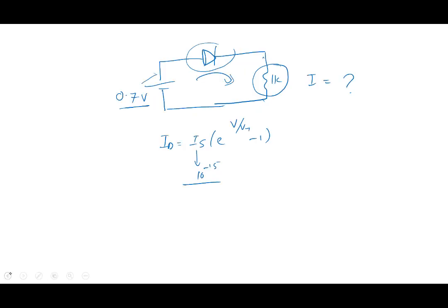The drop is going to become small here. For example, let me take an extreme case. Suppose somebody did ask you to calculate for 0.3 volt. How much current will flow in this particular circuit? 0.3 volt. Now, what we could assume is the current is going to be very small. Why is it going to be very small? Note that this current ID is 1 milliampere at diode voltage equal to 0.7. The diode voltage will obviously be less than 0.3. At the most it would be 0.3.